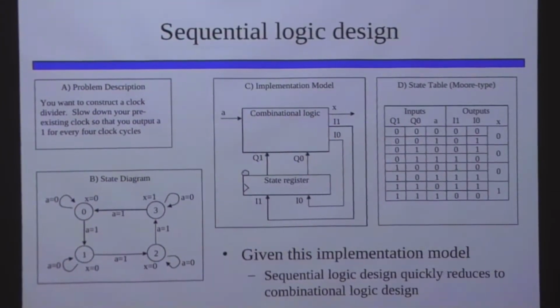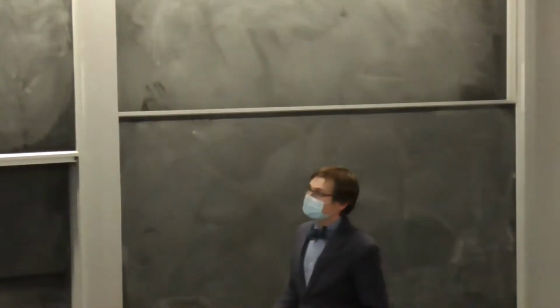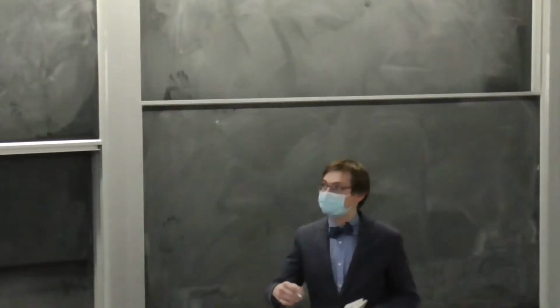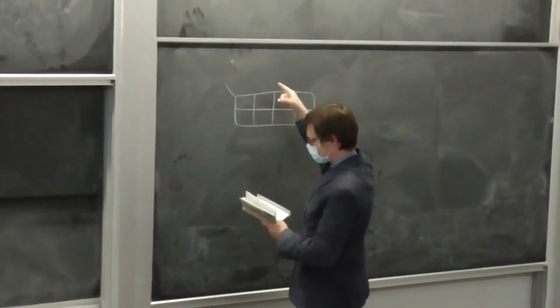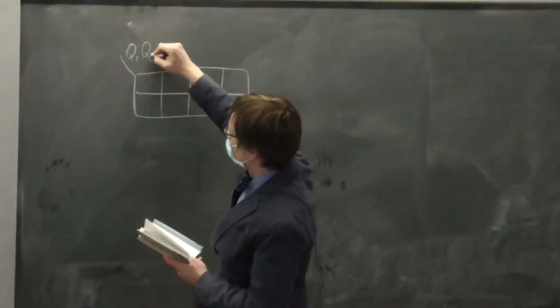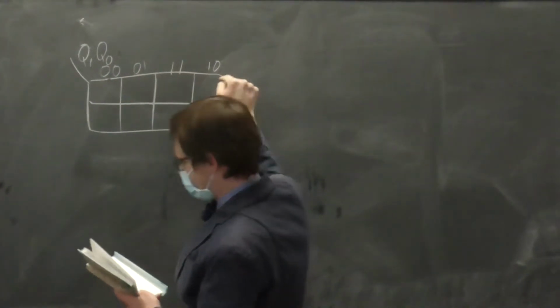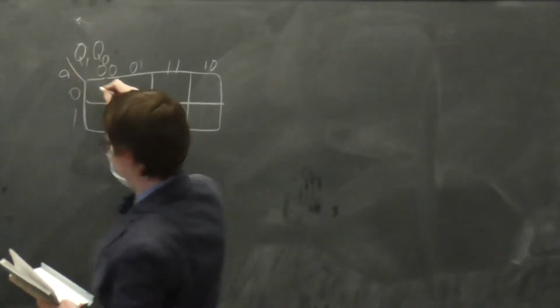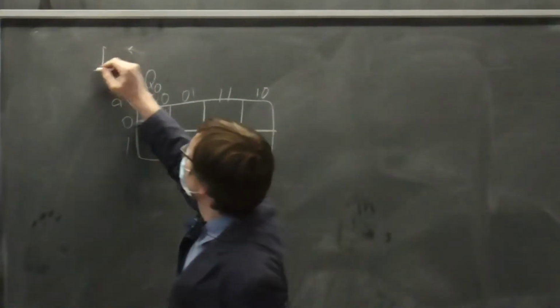It's another one of my famous pull out my notebook moments. So let's deal first with the output I1, right? If we represent this in sort of the, I don't know what you call this, table with a tag, with a whatever you call it. We're going to do Karnaugh map. Just immediately jump into the Karnaugh map, not mess around. Gray coding, very important. So when our inputs are 0, 0, 0, what's our output for I1?